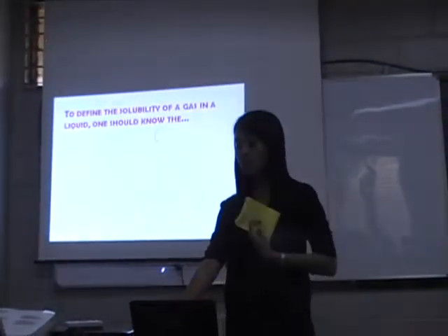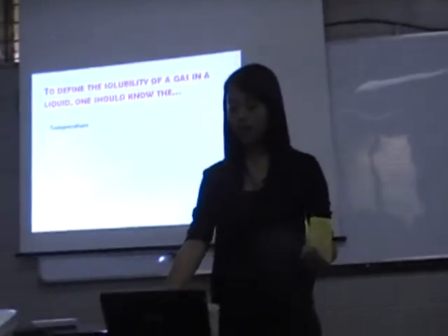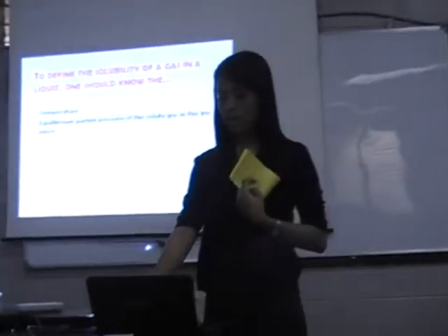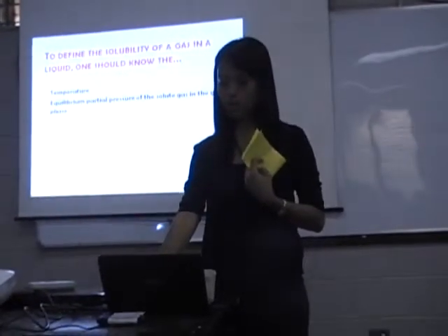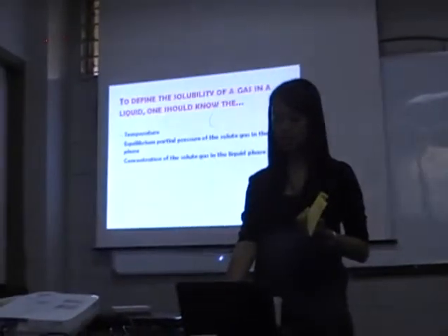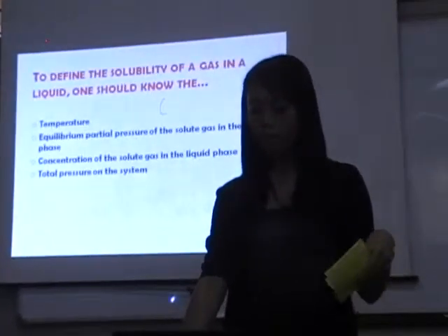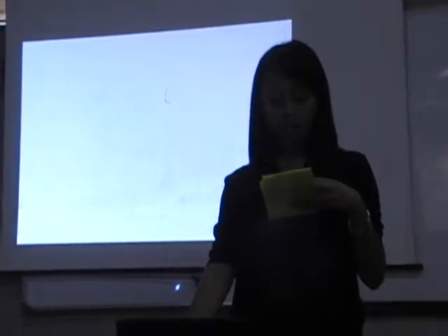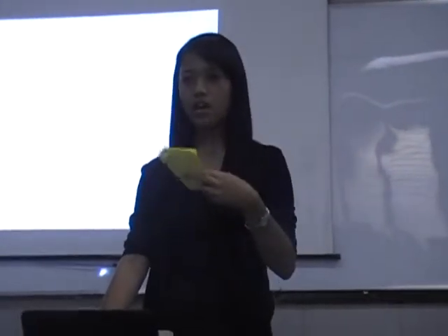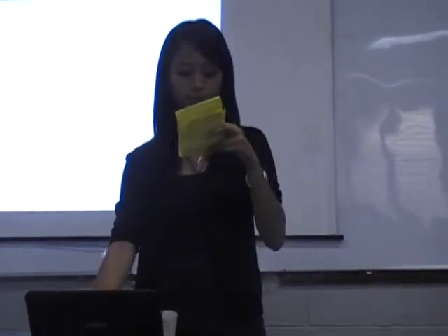So, for us to define the solubility of a gas in a liquid, one should know the temperature, the equilibrium partial pressure of the solute gas in the gas phase, the concentration of the solute gas in the liquid phase, and of course, the total pressure of the system. So, kailangan din natin ng selection of the solubility data when considering the general design of the gas absorption.